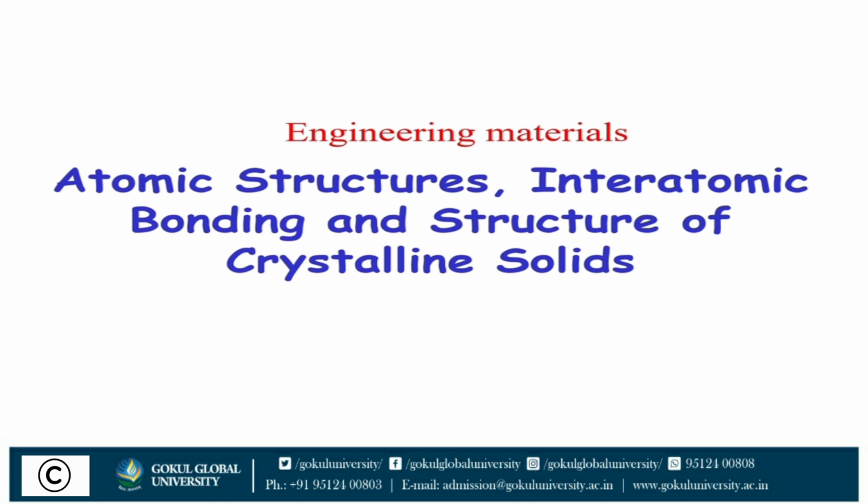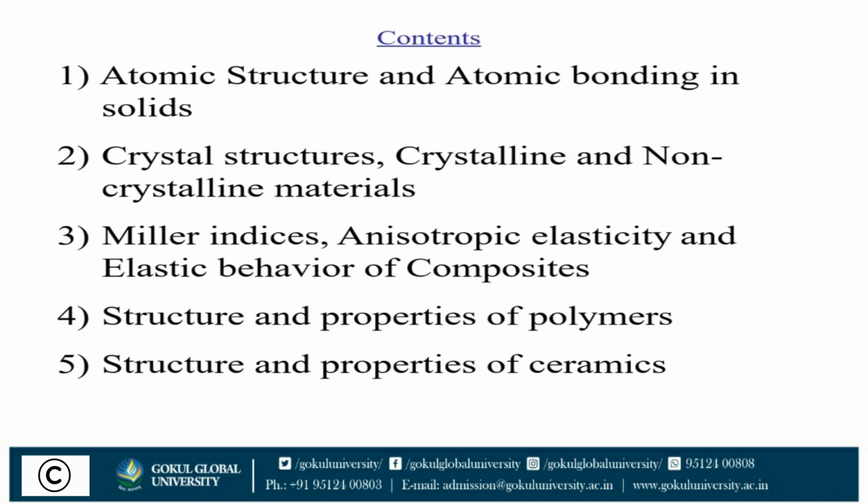It may be metal and non-metal. The metal may be classified into two categories. It may be ferrous materials and it may be non-ferrous materials. The ferrous materials are those which have iron as the main constituent, such as cast iron, wrought iron and steel. The non-ferrous materials are those which have a metal other than iron as the main constituent. Then it is copper, aluminium, brass, tin, zinc. These are all examples of non-ferrous materials.